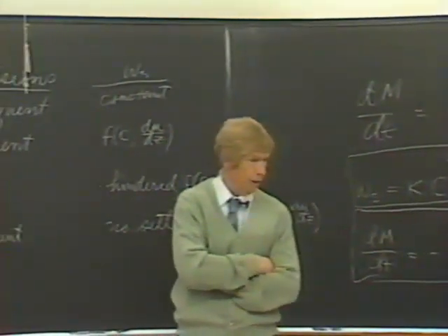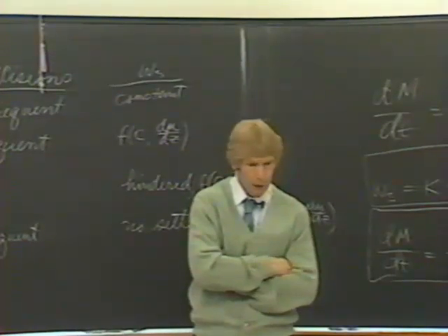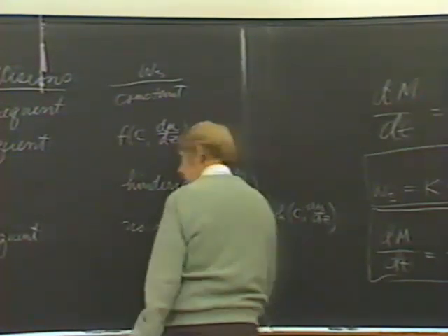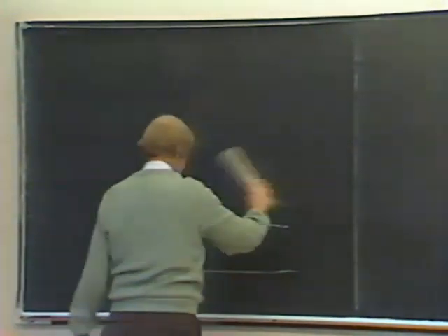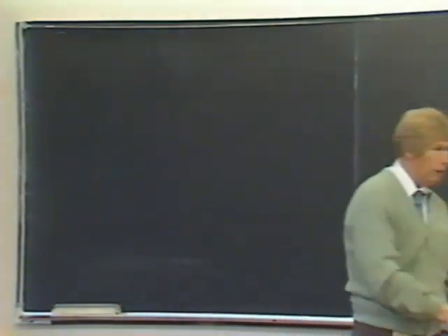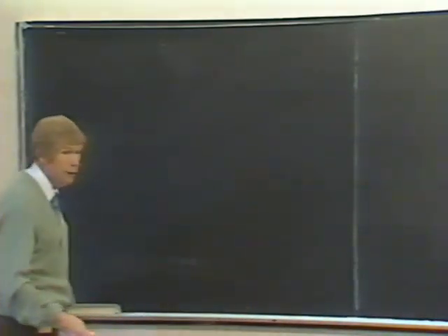So that when you go out and take measurements of settling velocities using an Owen tube, it's important that you recognize the system that you're in and take suspended solids or settling velocity measurements at the appropriate place and the appropriate times. And it's a good idea to take them as a function of concentration, so you can see how they change with changing concentration and velocity gradients. Then you can empirically represent that in your model. Do you follow me? I'll bring you a paper next time that describes that a little better than I could do it verbally.